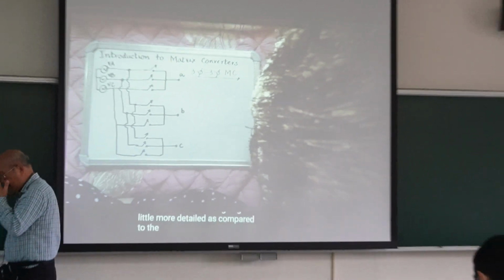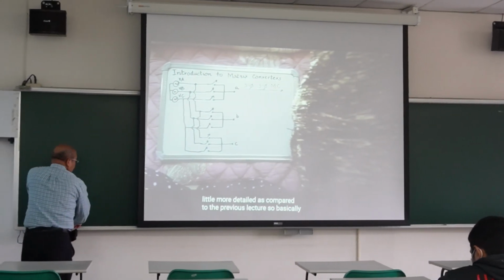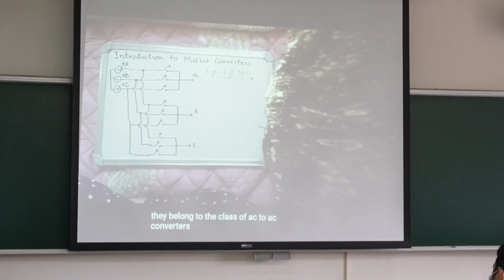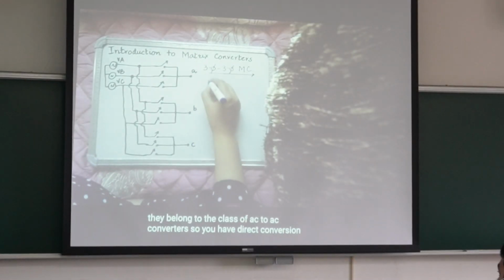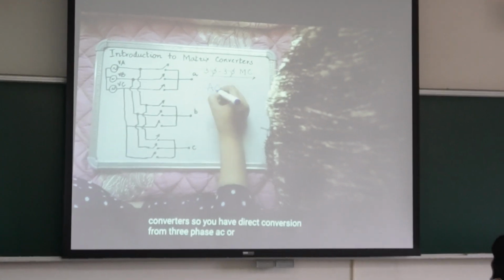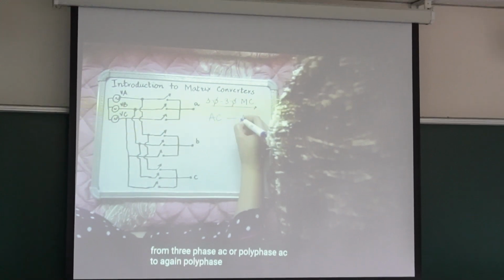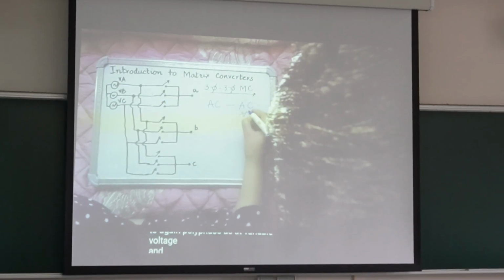As compared to the previous lecture. So basically, what are matrix converters? They belong to the class of AC to AC converters. So you have direct conversion from three-phase AC or polyphase AC to again polyphase AC at variable voltage and variable frequency.